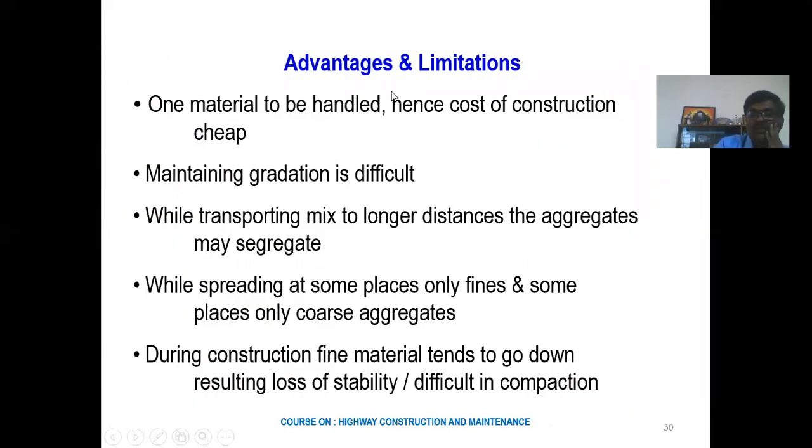So what are the advantages of the crusher and macadam? We are handling one material, hence the construction cost is cheap. But again, there are limitations. Maintaining the gradation is very difficult, because we are transporting the dry mix directly to the job site, and then we are paving or spreading using the grader, and then we are sprinkling the water and then rolling.